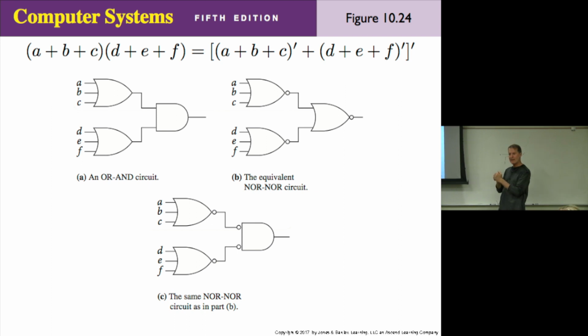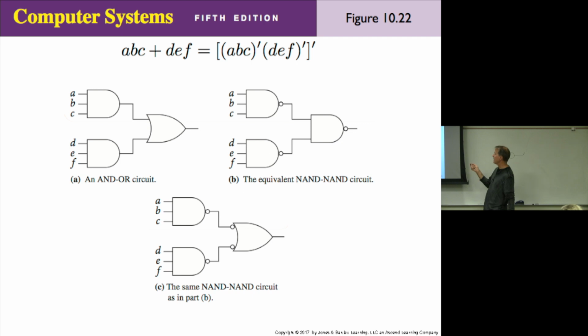Okay, in the NAND, do you use the NOR gate? Because that's the same thing, or do you want it all with NAND gates? All with NAND. You mean inverted input? Yes. Wait, let's go back. Did you have a homework assignment that used this principle of figure 10.22? Yes. So if you draw C, is that okay, or do you want it to be all the same as B? Either way is fine, because they are equivalent, because this gate is that gate.